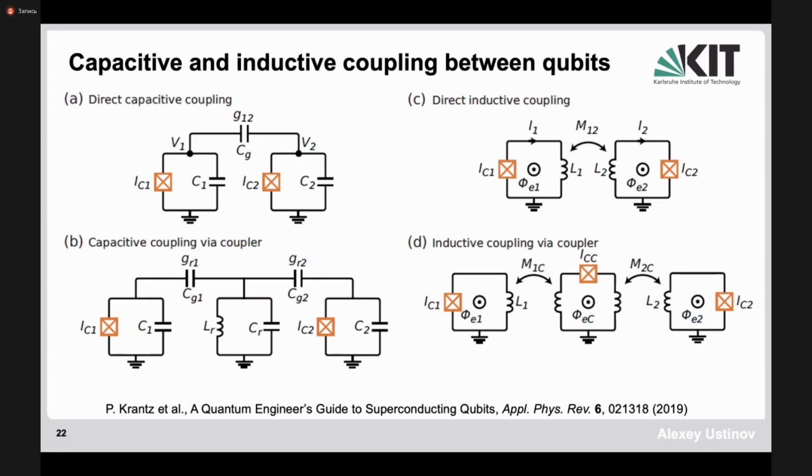It's also compatible with conventional signals, which are usually not currents, but rather voltages delivered by semiconductor devices. Semiconductor devices can have very high impedances, mostly manipulating with electric fields rather than magnetic fields. Magnetic coupling is more tricky because one has to observe the magnetic flux quantization in superconducting loops, which makes the design not simple. And therefore, magnetic coupling is strongly non-local. Magnetic fields, as you know, are generated by currents and not by charges, and there are no magnetic charges.